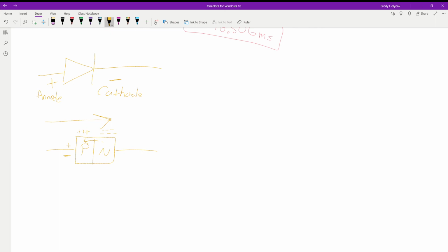And with diodes, like I said, they're based out of silicon, but we have a couple of different flavors. We can make them out of silicon, or we can make them out of germanium. There are still some others, but the primary two we use are silicon or germanium diodes. The difference in materials is that germanium diodes cost a little bit more, but they have a smaller voltage drop. So when they're on, they're going to require a certain amount of voltage. For silicon, it's a 0.7 volt drop.